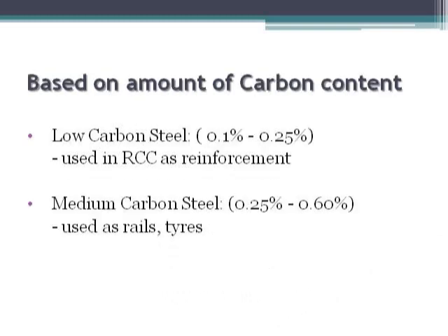And the second classification is based on carbon content. As we increase the carbon content, the toughness will increase, the strength will increase, but the ductility will decrease. Okay, so the ultimate yield and ultimate tensile strength and hardness of the steel increase, and ductility and toughness decrease when more carbon is added to iron.